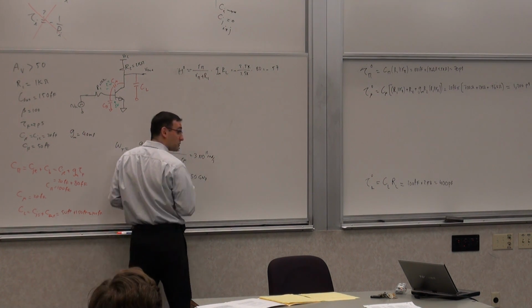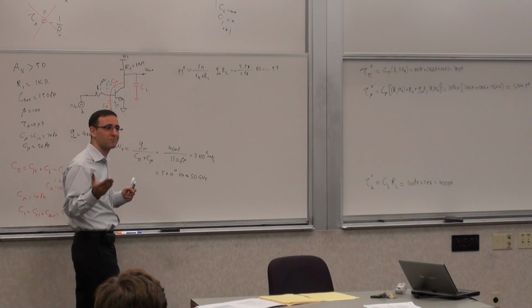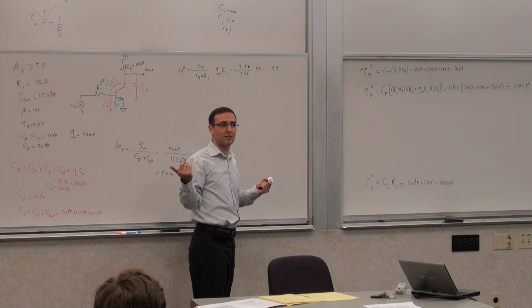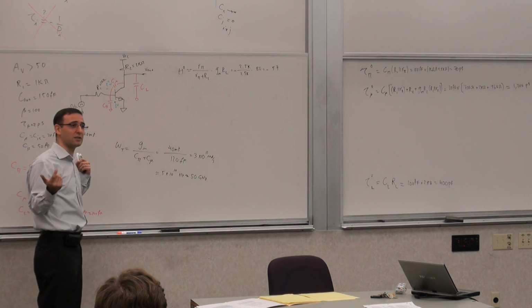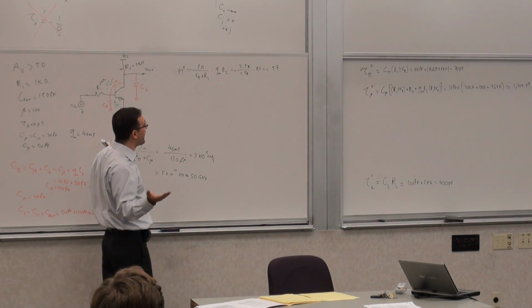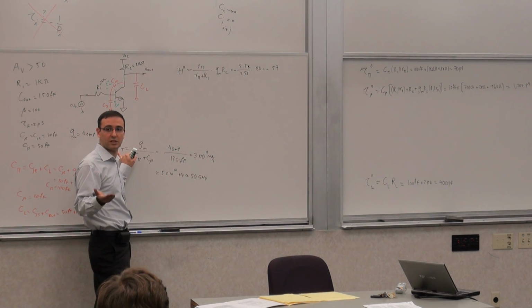So you took a transistor whose cutoff frequency was 50 gigahertz, and you had an amplifier whose 3 dB frequency is 100 megahertz. You have to remember, this is a 3 dB frequency, right? So its cutoff frequency is, you can calculate its gain bandwidth product, because the gain here is 1. It's the unity current gain.